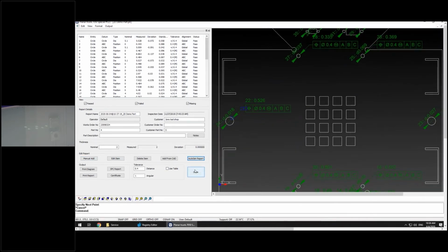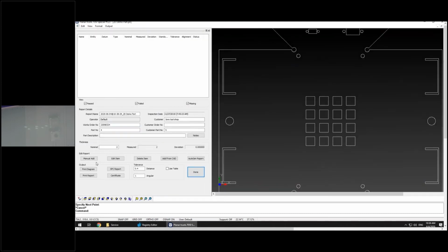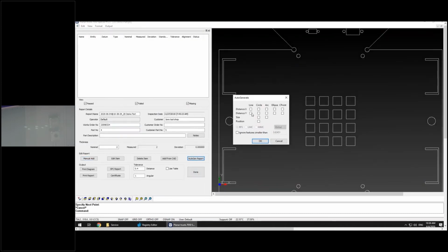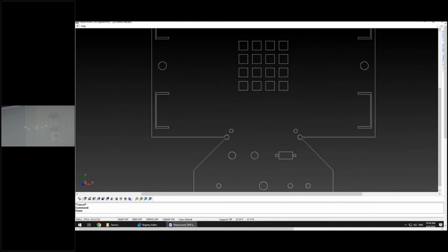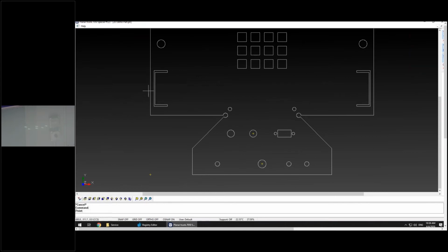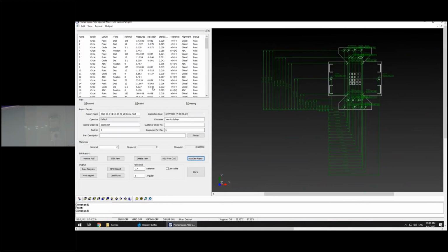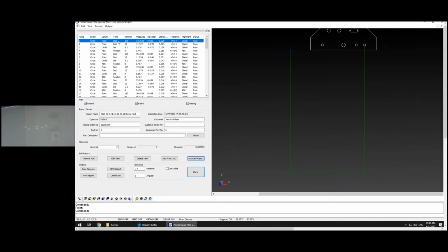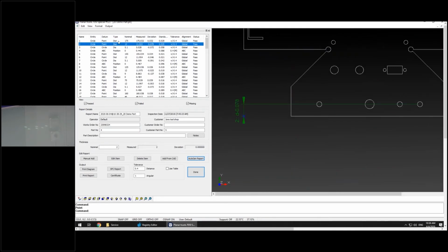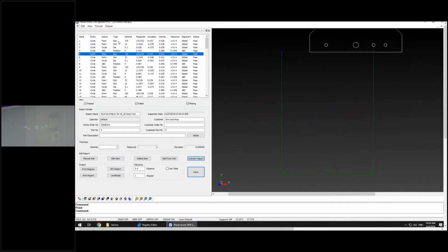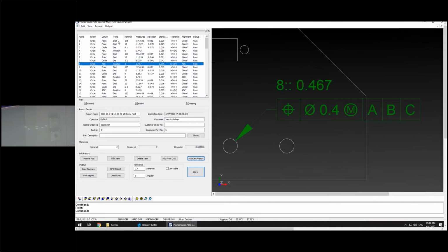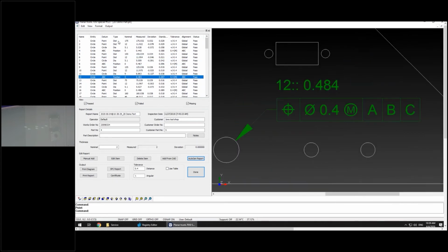If you really want what you guys are probably looking for, which is true position with the XY location, because maybe that's something you want to know as well, do circle with position to MMC to ABC, hit OK. Again, select my datum point. I'm going to specify that's my C and that's my B. And now, as I start down, this is my X location to that hole, my Y location of that hole, size, and position value. Next one is going to be, again, X, Y, size, position. So they've changed up the way that they actually make the inspection report as well.